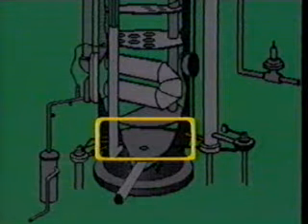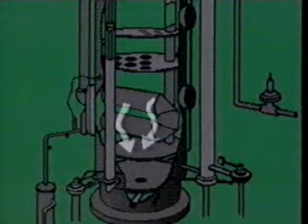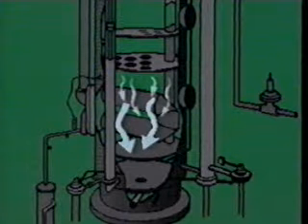Located in the very bottom of the heater treater, the free water knockout section allows the water to settle out and finally leave the vessel through the water dump valve. In water washing, large water droplets coalesce with small water droplets and settle out.